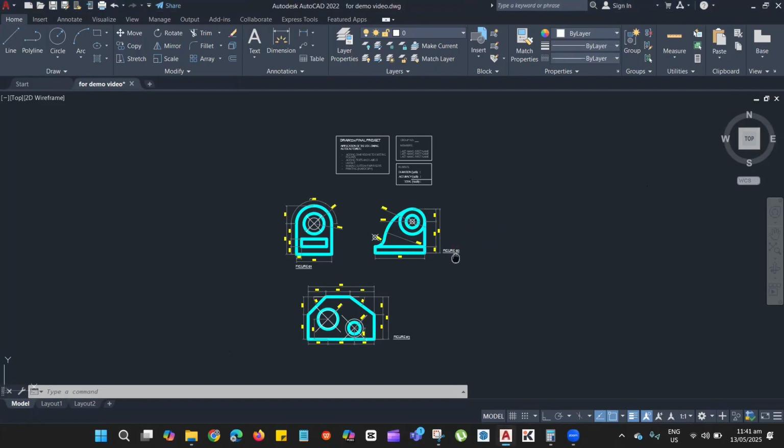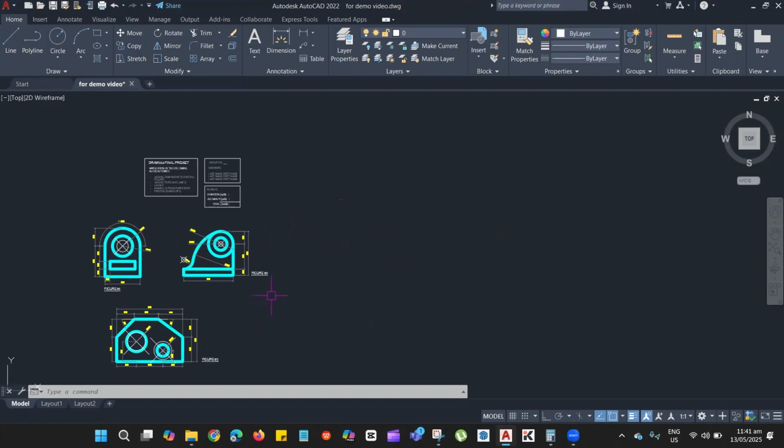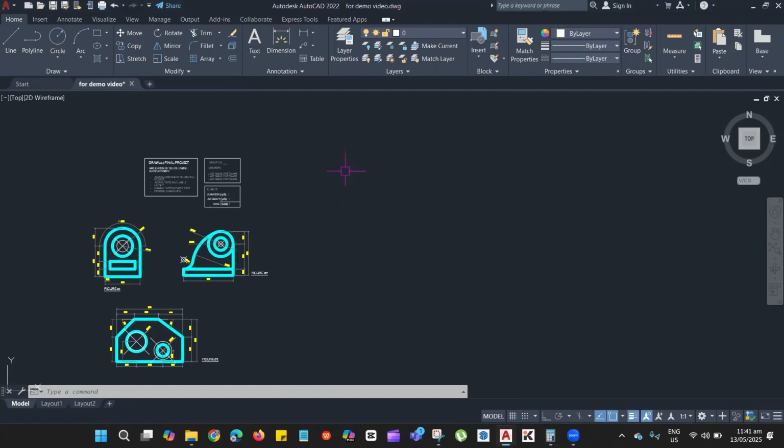First things first, you need to decide on what paper you want to use. These drawings are already pre-scaled, so it's going to be really easy. So let's use 8.5 by 13 paper size. If you convert that, just get your calculator and multiply 8.5 inches by 2.54. That should give you 21.59 cm.